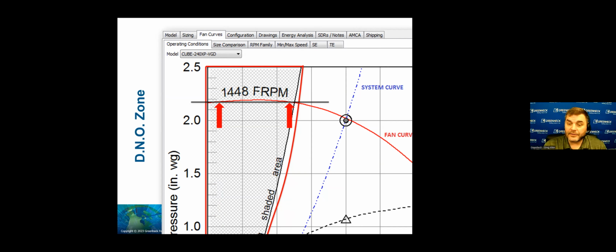The reality is the fan doesn't know and neither do I. It's going to try to do both. Unfortunately, that doesn't mean it's going to move 800 CFM. That's not additive. What it's going to do is called hunting, right? It's going to load up, move that 700 CFM, and then all of a sudden it's going to unload and move 100, and then it's going to build back up to 700, and then unload again. It's going to hunt back and forth across that fan curve.